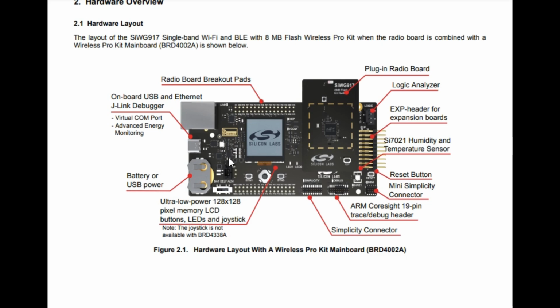In this main board, you have a USB Type-C connector, using which you can use it as a COM port to transmit and receive signals. This COM port is also called a virtual COM port, and this helps you plug in power to the board and also serves as a UART.